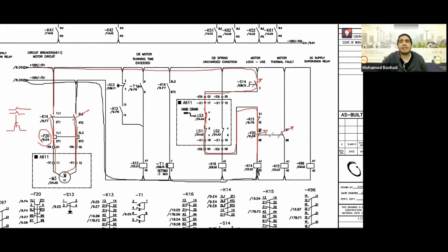What is this contact? These are two contacts, and when it sends them to you, they are like dashed lines, indicating that the two are connected to each other by the same system or the same components. If any of you work with control circuits and PLCs, you will understand that the overload always comes with terminals 95, 96, which are normally closed, and 97, 98, which are normally open. They are now drawn with one normally closed and one normally open. The overload is depicted in a state where everything is healthy.